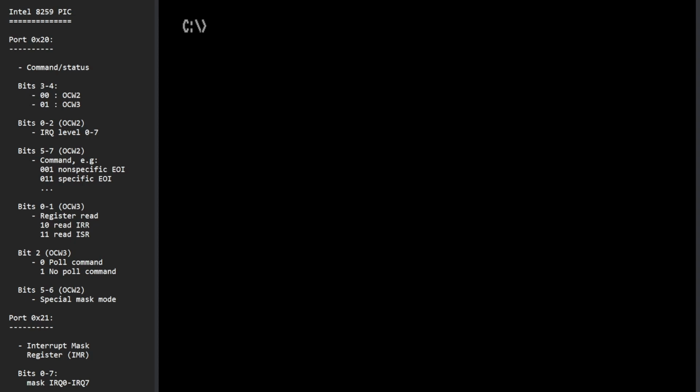So what we've done is we've turned off all of the interrupts except for two. One of them is a timer interrupt, which we set up to run at exactly the same point every frame. And this actually wakes the CPU up at the start of our frame loop. And the other one is the keyboard interrupts. We've left those enabled because we want to be able to exit to DOS when a key is pressed, when the program is finished. But other than that, everything else is switched off. We even turned off dynamic RAM refresh, which also interferes with the CPU, or at least with the bus, and this has made the machine completely silent.